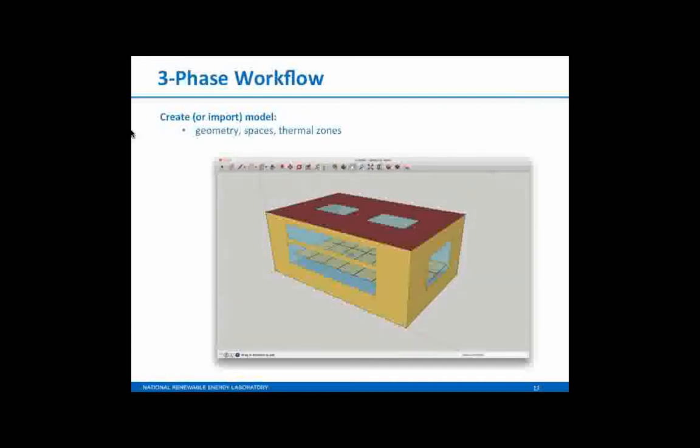So we have a luminance map object, which basically just defines a grid of points that we want to analyze. There's a daylighting control object, which dictates what happens to the lights. That's where you can set your set point to turn the lights on or off in response to that available daylight. This is kind of the whole point of doing all this Radiance simulation.